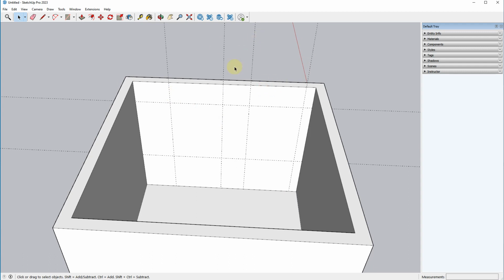So with these rulers that I've just put down, basically I have the box right here for a 3 foot by 4 foot window, and then I have a 3 foot by 6 foot 8 door. So I can use the rectangle tool, and I can draw. Oops, missed that intersection. Just draw that right there, draw that right there, and then I'll use the push-pull tool